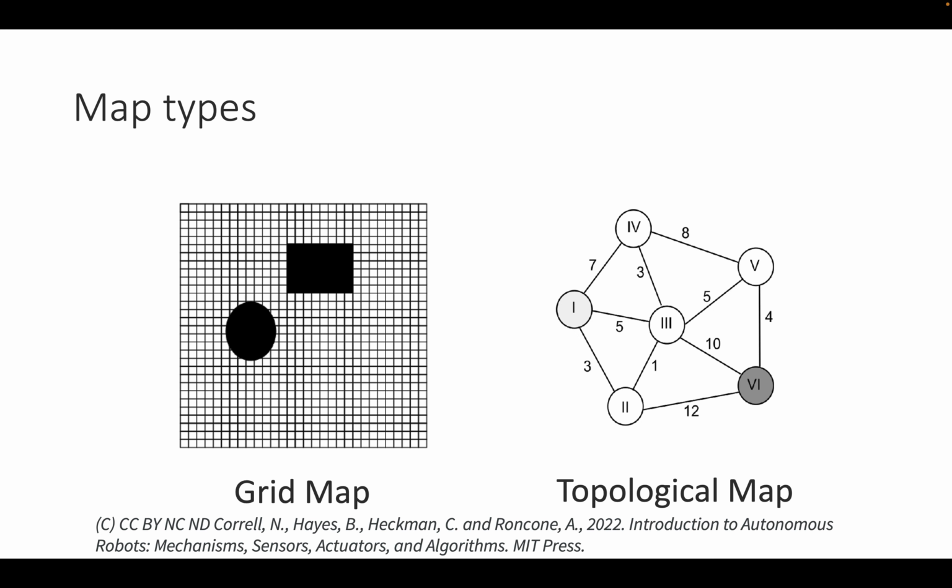The grid map is a pixel-based map that you would use in the local vicinity of a robot. For example, you have a vacuum cleaning robot in your living room, or you have an autonomous car that has been navigating through a city using a topological map. It will then need to create a grid map, or in that case a voxel map in 3D, of its environment to plan locally where it can drive.